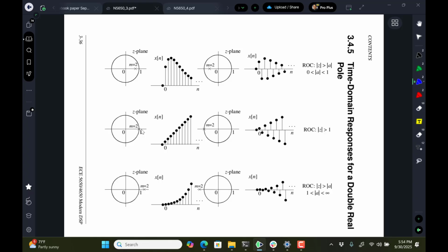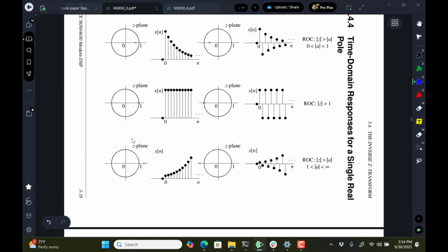I don't know if this kind of hits you in any particular way, but to me it goes back to something when I first learned about S-domain things. They would talk about the situation of conditional stability. So a person might say this would be conditionally stable because, if this were a system that had a pole right here, as long as the driving waveform wasn't going to resonate by putting a pole right at that location, this output would not go unbounded. It would just have a constant value.